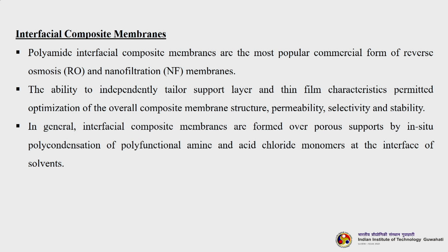Now, polyamide interfacial composite membranes are the most popular commercial form of RO membranes as well as nanofiltration membranes. The ability to independently tailor support layer and thin film characteristics permitted optimization of the overall composite membrane structure, permeability, selectivity as well as stability. In general, interfacial composite membranes are formed over porous supports by in situ polycondensation of polyfunctional amine and acid chloride monomers at the interface of the solvent.